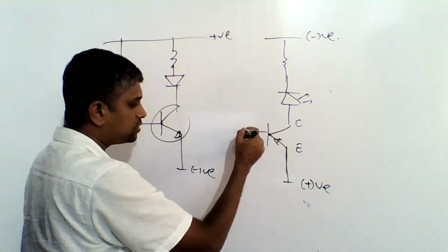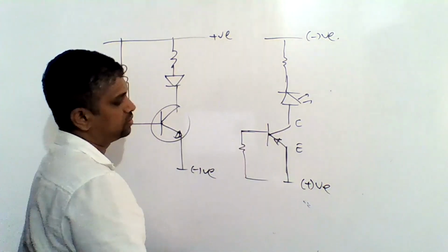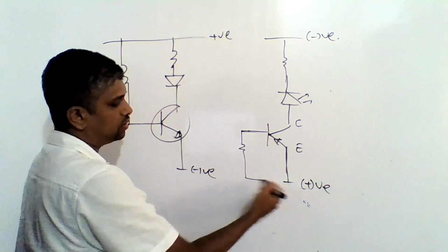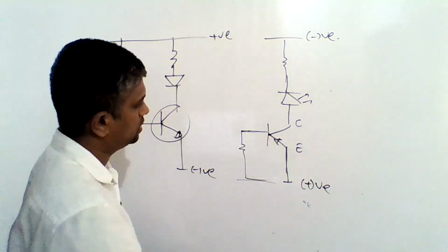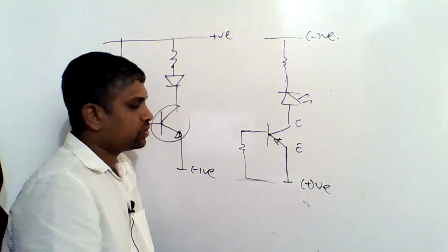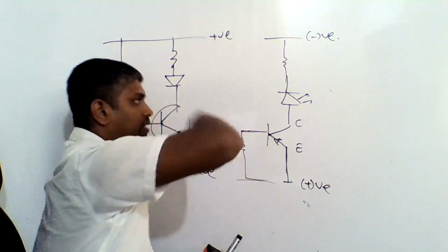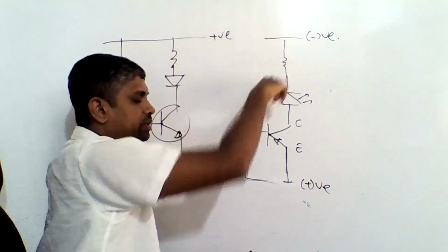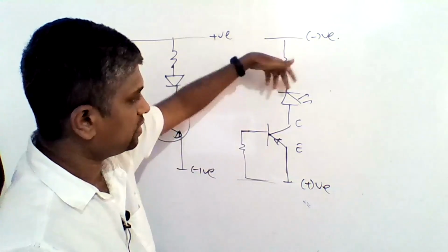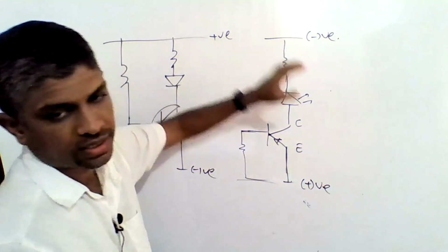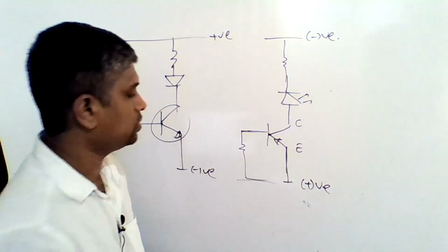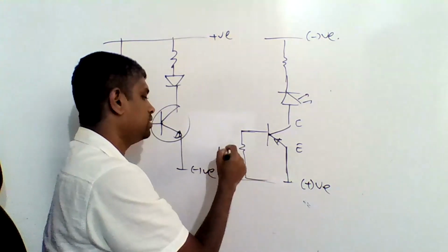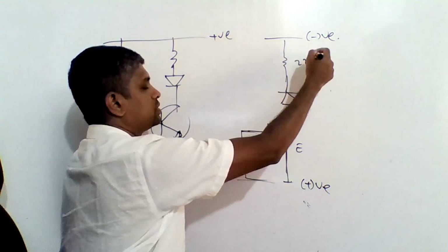And you must connect this resistor to the positive terminal. That's how you have to construct. This is what we connected the other way round earlier, because we maintained the same LED direction. You can try this circuit also. You can use 100K here and a 220 ohm resistor.